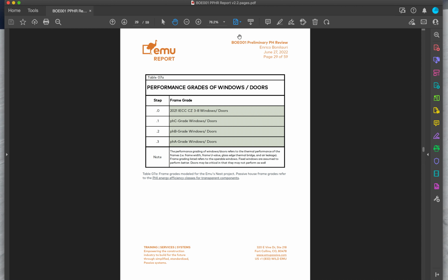I recommend you take a look at all these attached documents. A good quality window is not just a triple pane window. We have a whole course describing that, and once you switch to triple pane, then your frame becomes the weak point. So we look at the specific thermal quality of the frame, so that you can make a decision that is consistent with your thermal needs in terms of thermal comfort, as well as what you can afford in terms of feasibility, and what fits the aesthetics and design of your project.